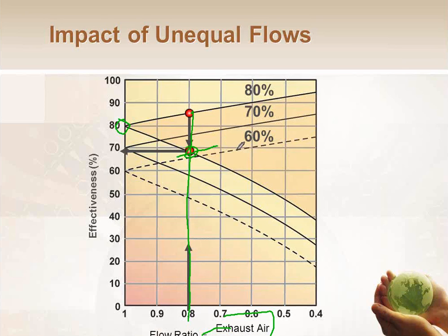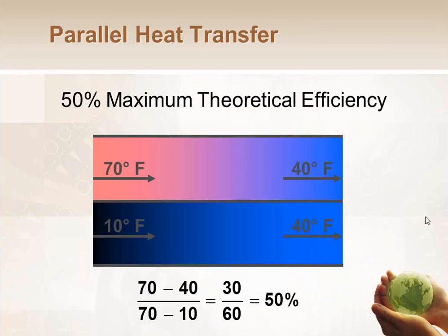It's just that I need to know that when I'm doing the math, when I'm sizing my HVAC equipment, I'm not going to get 80% recovery. I'm only going to get 64 in this case. But I do have to keep some buildings positively pressurized. The best I could possibly do would be 100%, and that's only if I put the heat exchanger in the correct place.